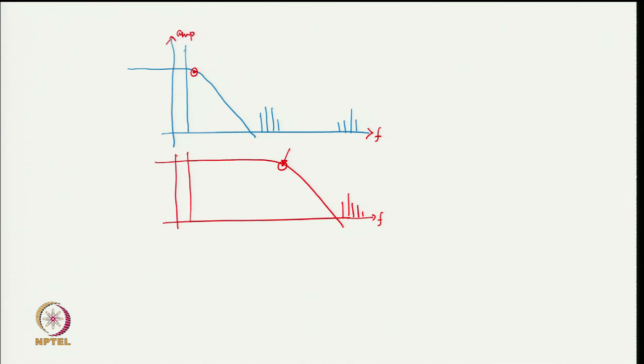So, the filter corner frequency can be shifted if the switching frequency of the converter is increased, and if we do this, the corner frequency shifts towards the right and the size of the filter will go down. We can also choose, for example, a third order filter or more instead of a second order filter, so that the slope here will change. That is also another option.